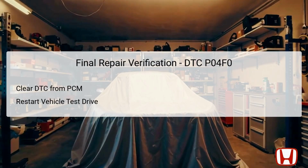Monitor the ECU, ensuring that no new DTCs appear during or after the test drive. If the system functions as intended and the check engine light does not come back, the repair is confirmed successful. Effective verification is crucial to maintain vehicle performance and compliance with emission regulations.